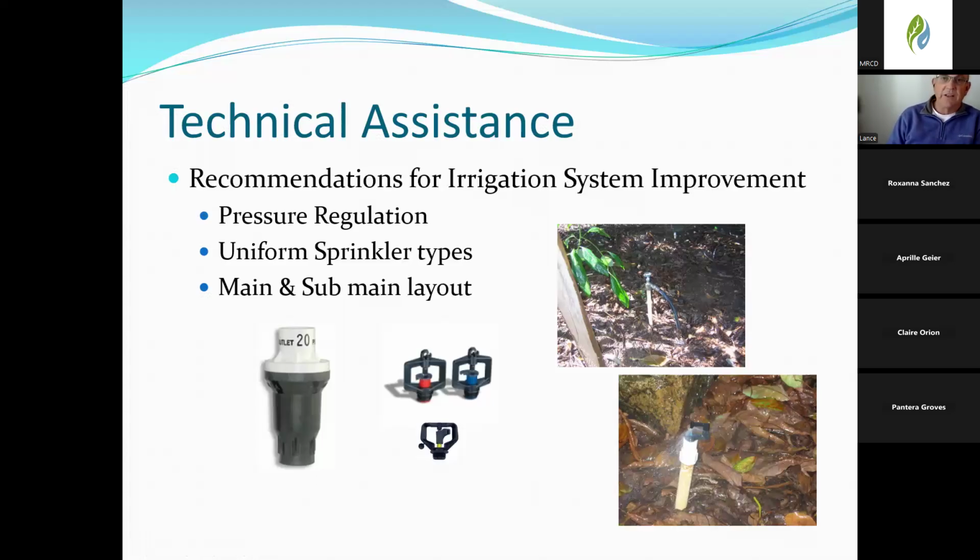And what that means is if you had 65 pounds of pressure at the bottom of the hill at the meter, assuming your meter, obviously sometimes they're at the top, but for our example, we'll say the meter's at the bottom of the hill, and you're running 300 feet of 3-inch pipe, and friction loss or pressure loss is measured per 100-foot section of pipe. So we'd have 3 sections. If we were 65 pounds at the bottom, I would expect in a 3-inch line to find 60 pounds at the top. We would only lose 5 pounds of pressure.